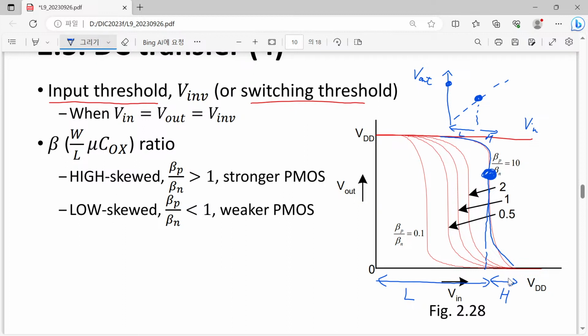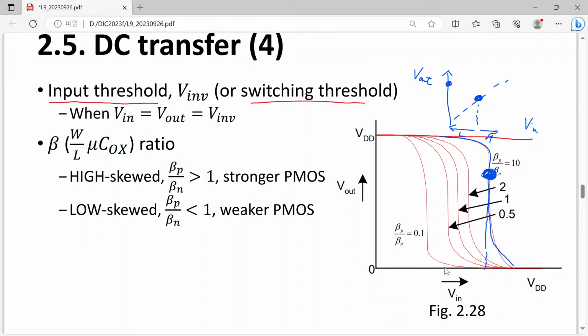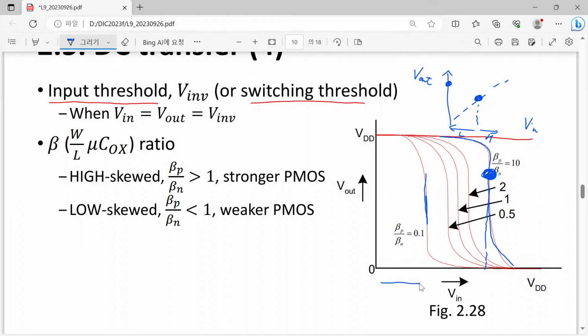When we have a random value from 0 to VDD, it is more probable that the random voltage is regarded as logical low. That is quite bad. Also, we have another different extreme. In this case, we have a much more limited range for logical low and much wider values for logical high. This is also not good.